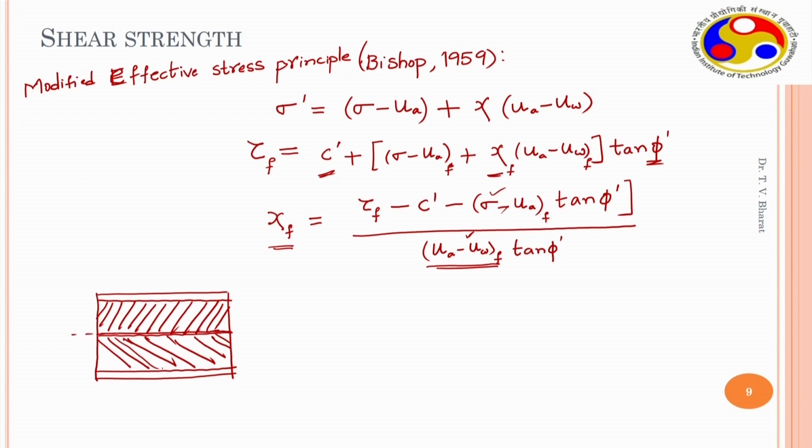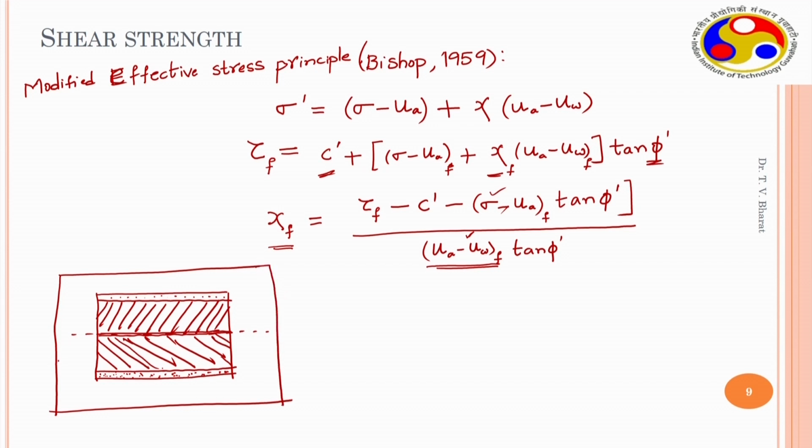So, this is a shear plane along which the shearing takes place when load is applied, and this is a coarse porous stone, and this is a high air entry disc. And here this whole thing is kept in an airtight chamber, and shear stress is applied, and this one box is confined. So, therefore, the other box can be sheared, and similarly you have dial gauges kept on bottom and top, and